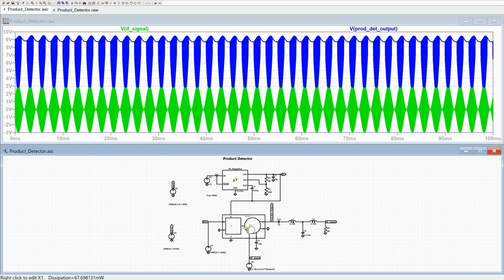So you have a sinusoidal signal, and half of the signal is passed. In this case, we have the bottom signal, which is passed. And so we still have a mixture of the message signal, which we can see. The message signal is the one over there at the top, and we also have the carrier frequency, which is going from 9 volts to 3, as we can see right here.